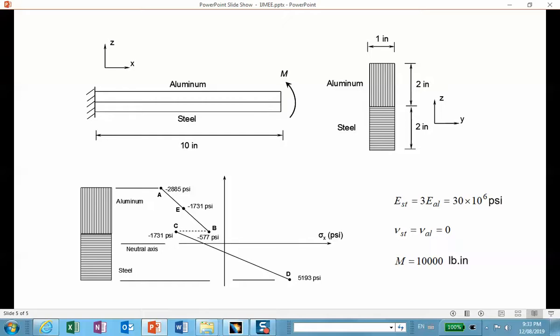Without finite element, you can approximate the stress distribution for a problem like that with the area transformation method. The plot at the bottom left corner is the information extracted from that calculation. The left side is clamped and the right side is subjected to a moment.